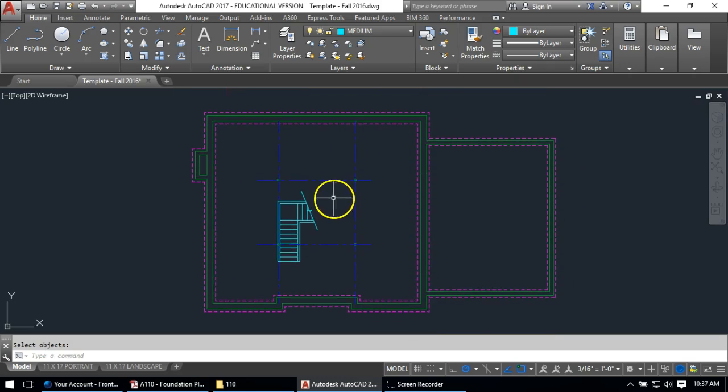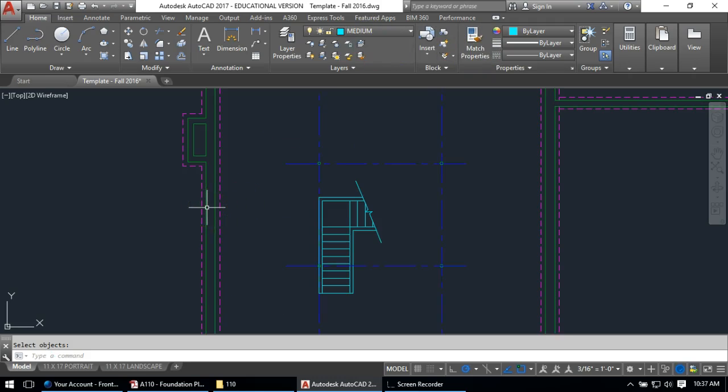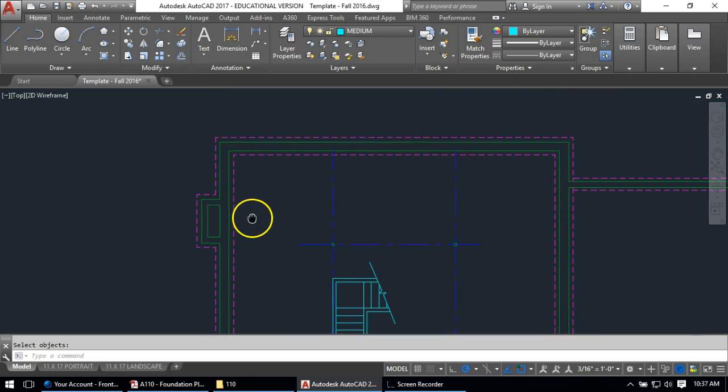A few more basic drawing components. We have the window. There's a set of windows, it looks like. Actually, there's a door and a window. It looks like the door is going to have that hexagon with the 1 next to it, and then the window is going to be the circle with the B1 over 48 inches there and there. So I think we're using the medium layer to draw doors, so I might as well draw the doors first here. And this door, if it comes down 11'6" from the top line, so I'm going to offset 11'6".